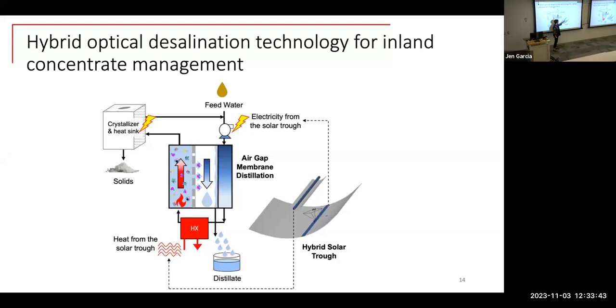And we have the secondary mirror, which I'll talk about in more detail. But this essentially acts as a filter to the photons and will redirect a portion of the photons that are most usable for PV back to our PV array to generate electricity. And then with the solar collector, we get process heat that we can use to drive our system.